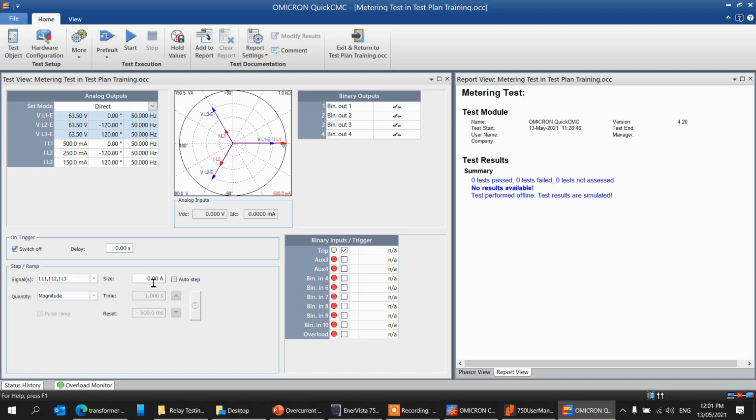Where do you press again, on the relay? No, on the software. On the software, you click by mouse or you enter some keypad, and then it will stop. You stop on the specific magnitude where you see that LED blinking on the relay. That's another one, and I think that's a quicker one. And the other one is you have to assign a specific contact for the specific pickup of that IDMT curve.